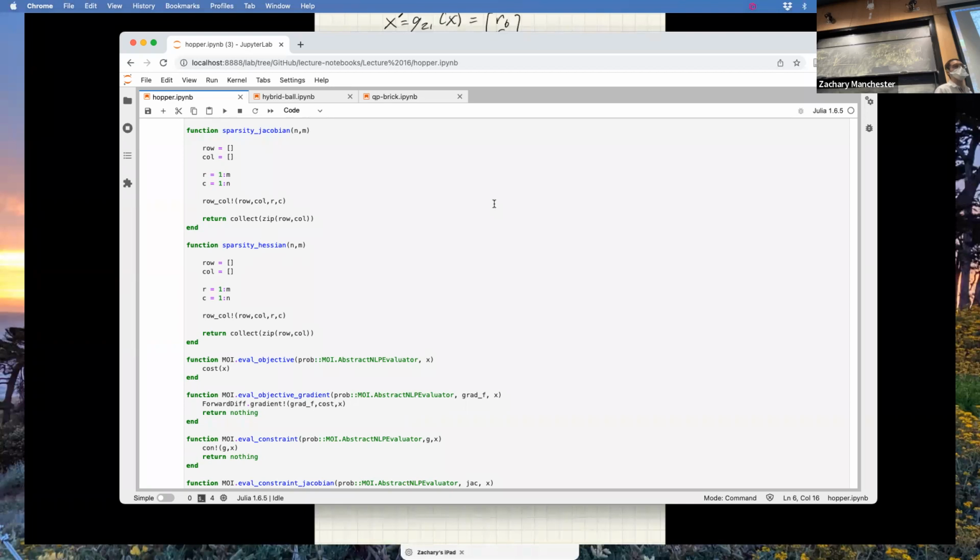Anybody else? Yeah. Can you make it do a backflip? Do you have a reference here? Oh yeah, for sure. We can make this do a backflip. I just have to sit here and play around with the cost function a bunch. Bonus points if you take this code and make it do a backflip. You definitely can do it. It's actually not even that hard on this one. It's pretty easy. You would basically give it a reference where the angle goes around 2 pi, set up the stance and flight phase stuff appropriately with the constraints and hit go, and it would definitely work. That one's not too bad actually.